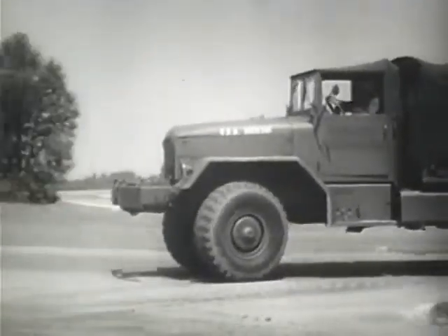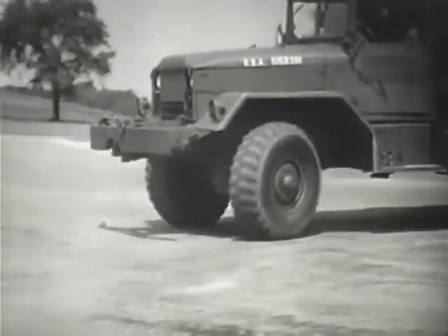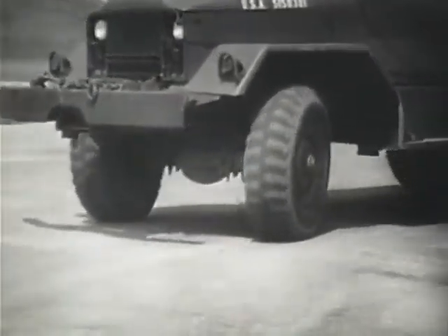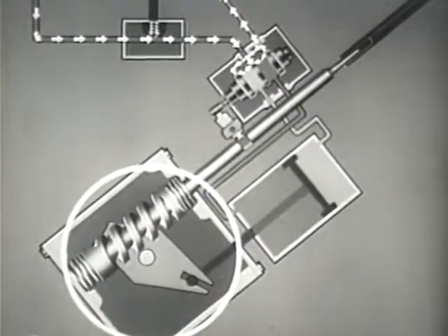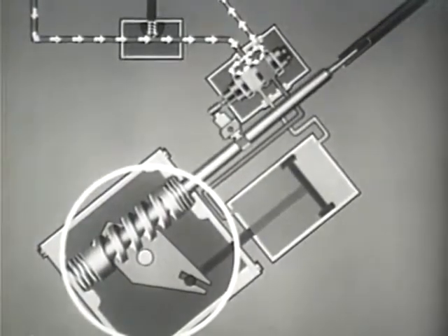When the front wheels are held in a constant turn, the cam will not be rotated. The pitman arm shaft lever is held stationary toward one end of the steering cam by the increased pressure on one side of the piston.